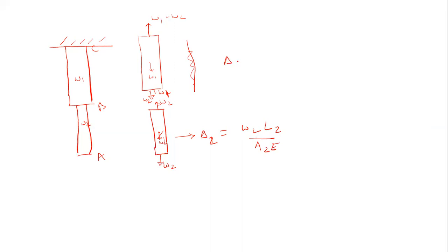And deformation for this section will be equal to W1 plus W2, because the total force acting is W1 plus W2. W1 plus W2 L1 upon A1E.